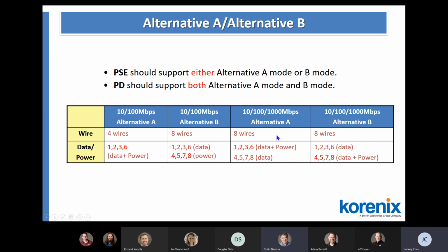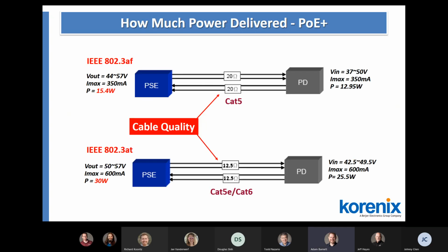And what's the distance, the line loss in the cable? How far can you go with PoE? Like Ethernet, it only supports 100 meters. 100 meters? Okay. I thought it was less. Yes, the maximum distance is 100 meters. Do you need a different type of cable to deliver it, like PoE versus PoE plus plus? Do you need to use Cat 5e or something higher? Oh, it's right there. Sorry.